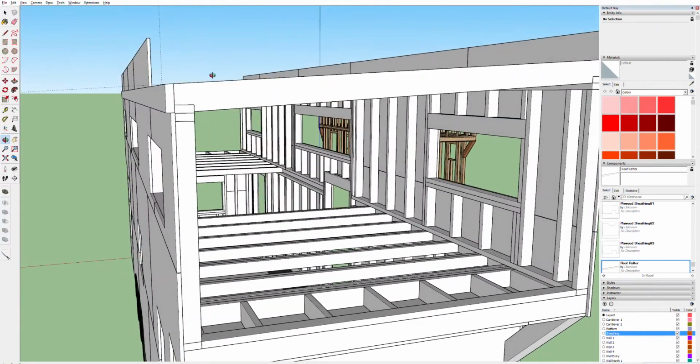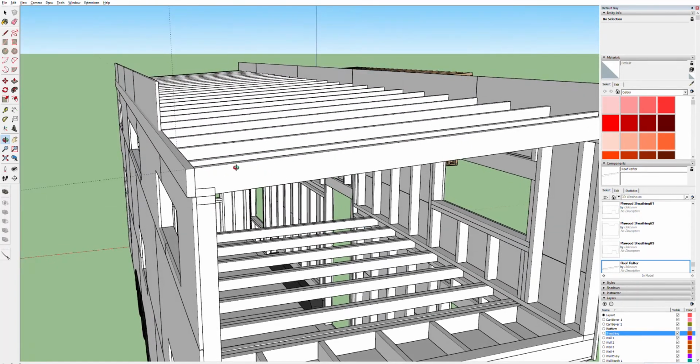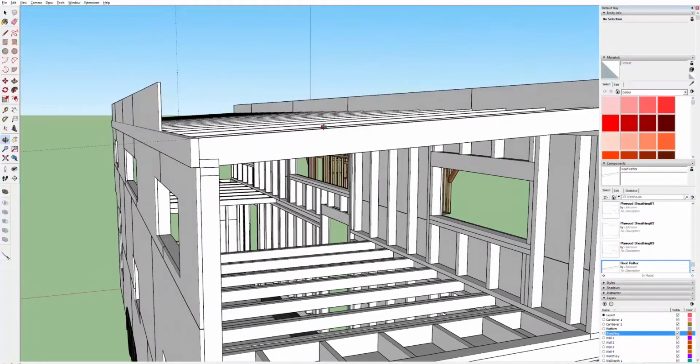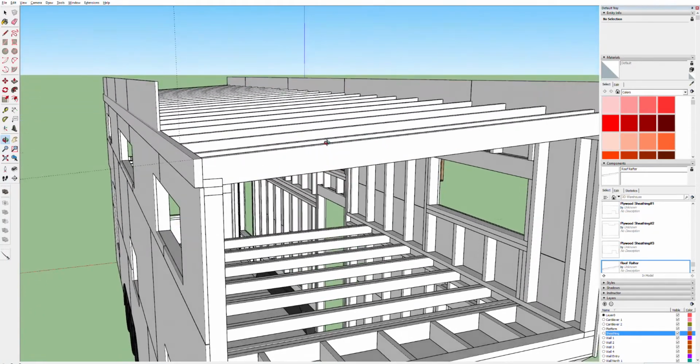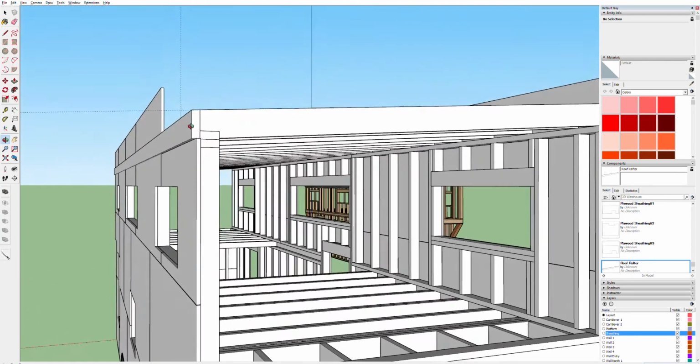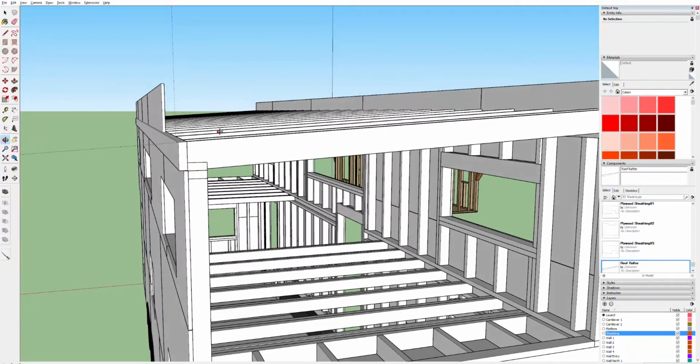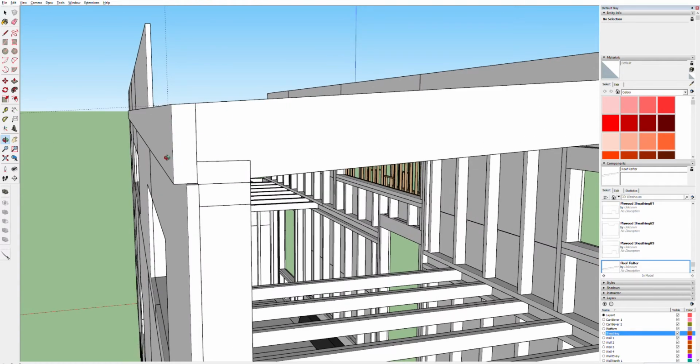Okay, so the purpose of this thing is that when we have our roof sheathing coming across, we're going to have our water barrier, something like felt, or I don't know, there's probably other stuff. It's not Tyvek for the roof. When we get our water barrier up there, we're going to have it come down and go over and staple it down to the bottom of this 2x6 right here.